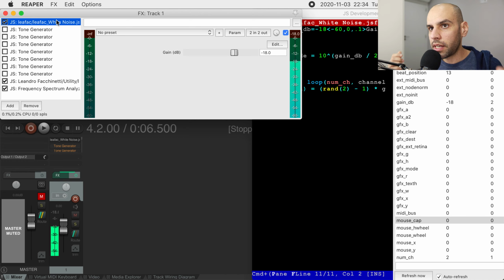So what we want is a plugin that is tailored for this task of burning in speakers, and it will be a white noise generator. In this case, I don't want it to be multi-channel, it will be only stereo, but it will be on the left channel some white noise, on the right channel that white noise inverted.